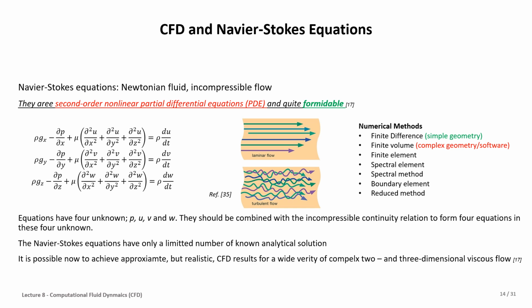Regarding CFD, the numerical methods are finite difference, finite volume, finite element, spectral method, boundary element, reduced method, and many other new approaches. And solving these complexities with these methods requires computation from high performance computing to be able to get the solution and the result from such a complex domain of the problem.